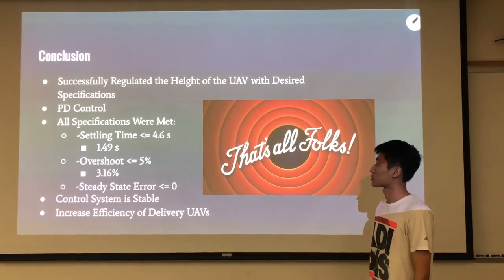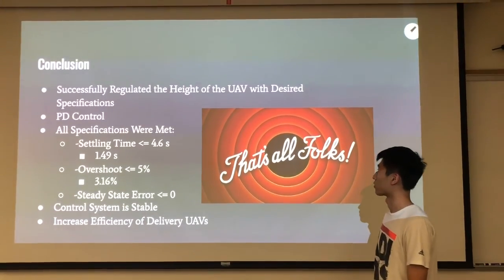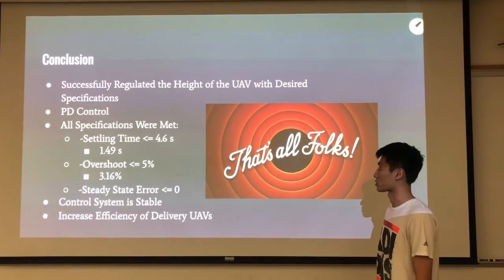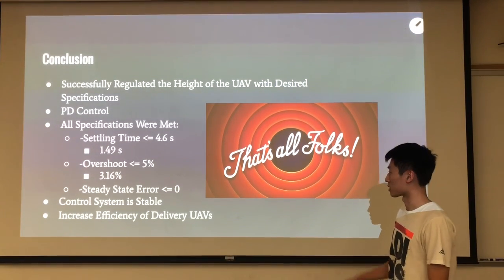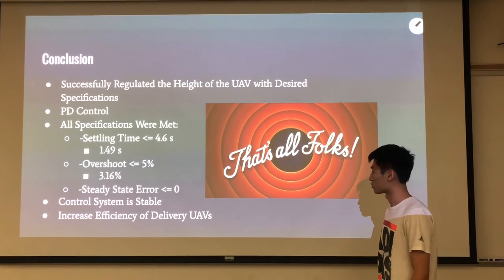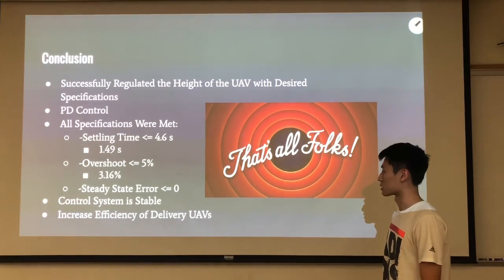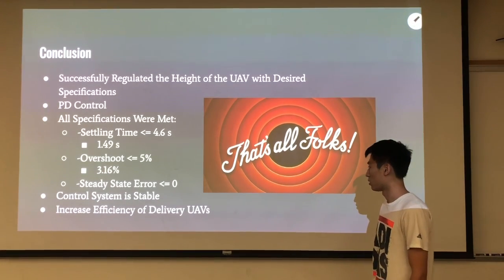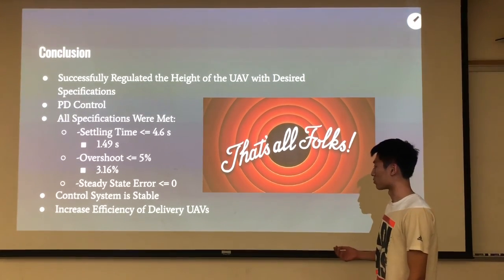In conclusion, our system successfully regulated the height of the UAV with desired specs through the use of PD control. All specifications were met. We have a really low settling time, virtually no overshoot, and a steady state error of 0. Our control system is also stable, which makes it a great tool to increase the